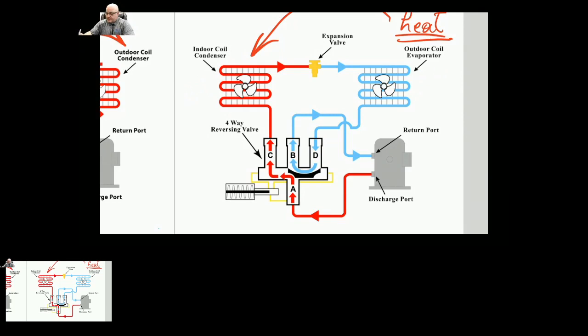So let's take an example that is known to everyone. We know 40 degrees Fahrenheit as an evaporator temperature for a certain refrigerant that we're not supposed to use anymore. If that's the evaporator temperature and the outdoor temperature is not higher than that, if the outdoor temperature is not 60 degrees Fahrenheit, you're not going to absorb any heat from the outdoors.